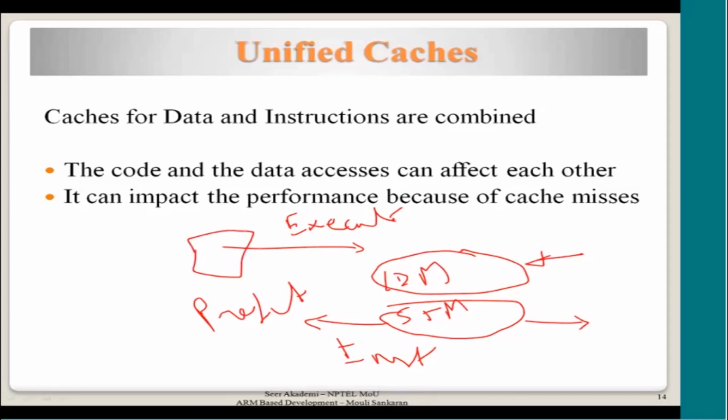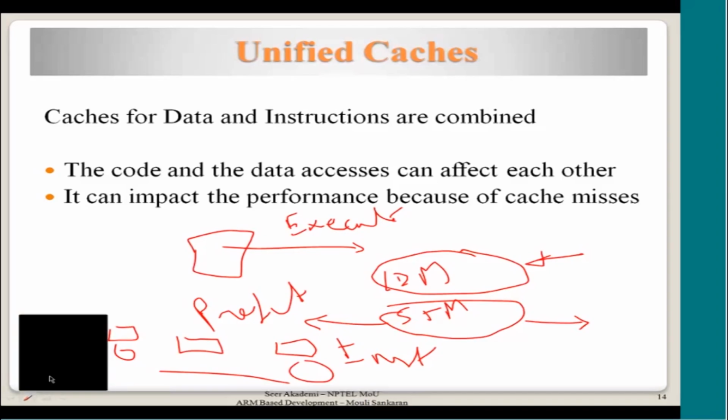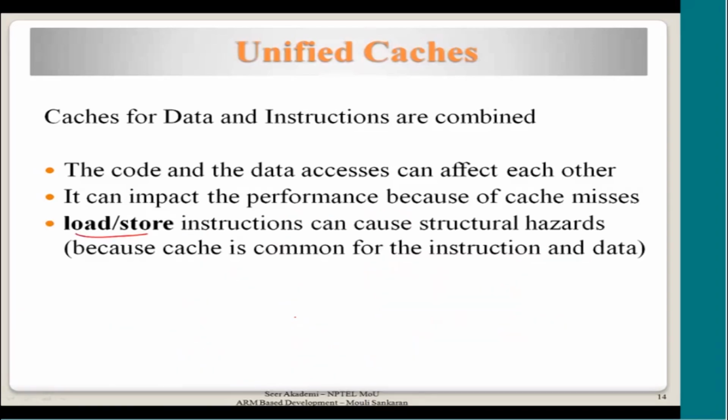So an instruction which is 3 clocks behind can come and cause a disturbance to the cache. Okay, so they are dependent. So load and store instructions can cause structural hazard because the cache is common.